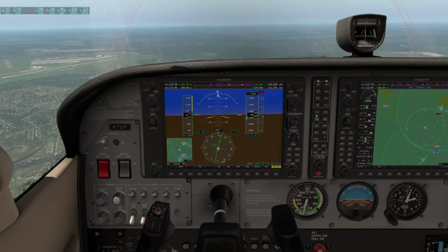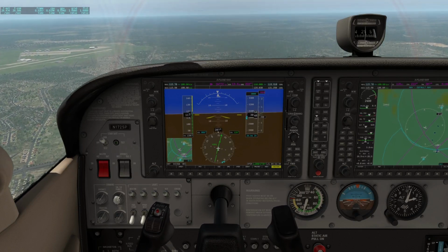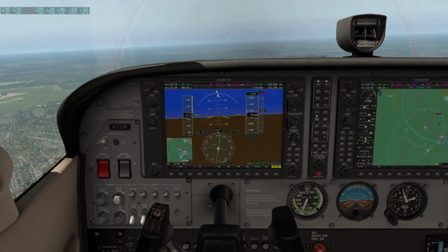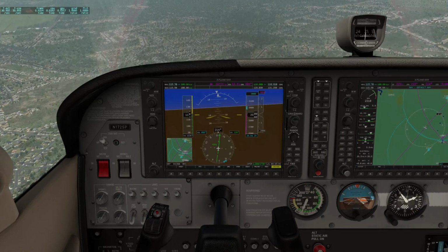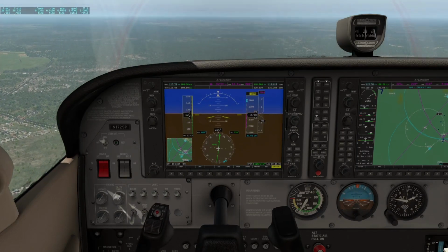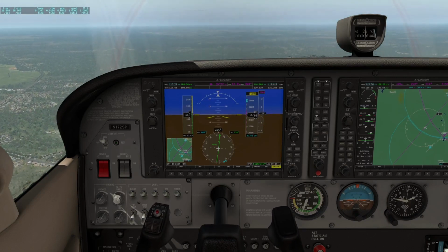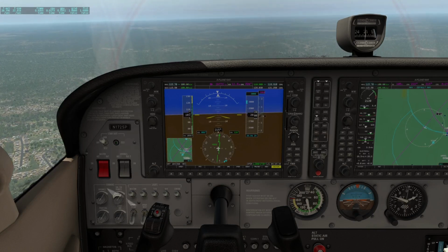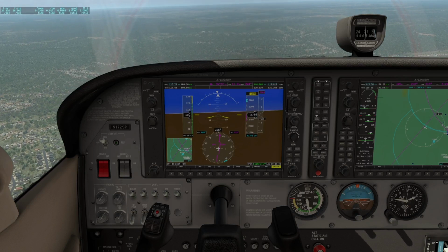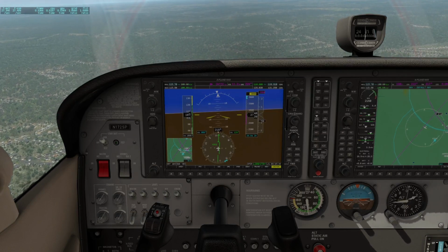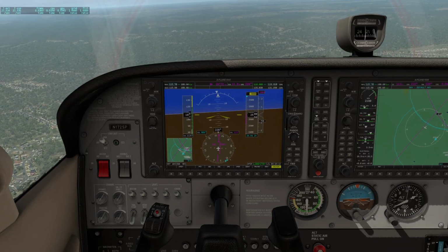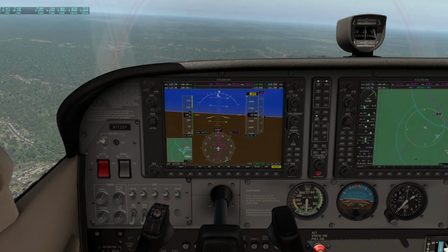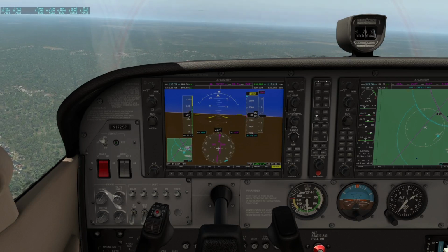We see our airspeed is indicating 114, 115 indicated airspeed, but we have a true airspeed of 120 knots. We'll decrease our engine RPMs. Pitch back up. While in flight, we can change from CDI VOR1 to VOR2, there's the GPS signal, VOR1, VOR2. So right now the way it's oriented, it should be trying to fly straight to Oxtick, which would be our next destination, the initial approach fix for the RNAV 23 approach into ELW, Anderson Regional Airport.